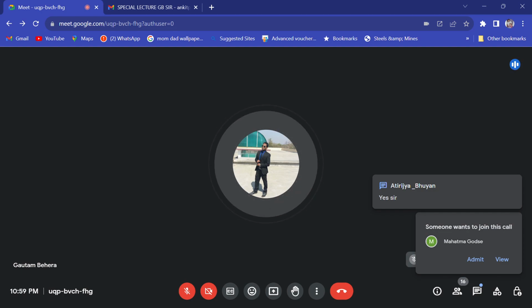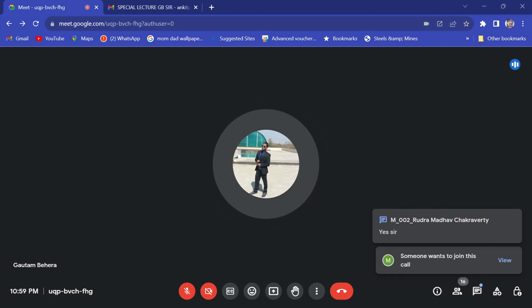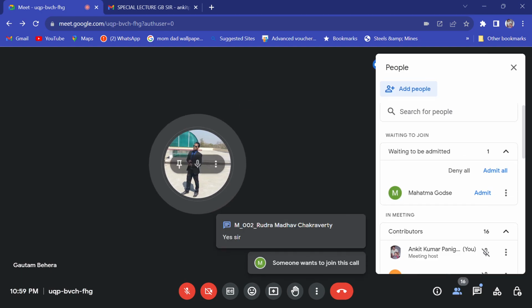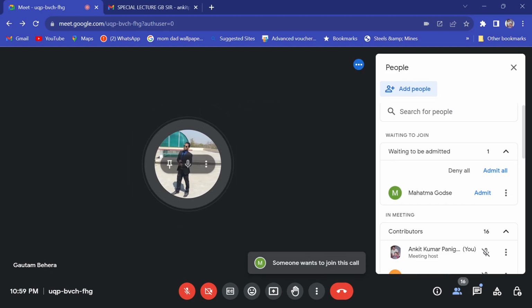That is called vacuum degassing. You have to apply vacuum so that the partial pressure of these gases will reduce and they will come out of the steel. This is one of the ways. So there are many degassing processes. Vacuum degassing means you just keep the ladle. Can you tell me what a ladle is, at least? What is a ladle?